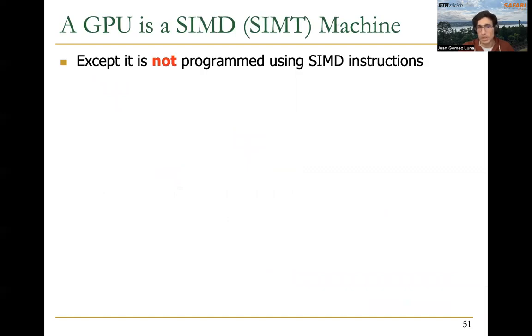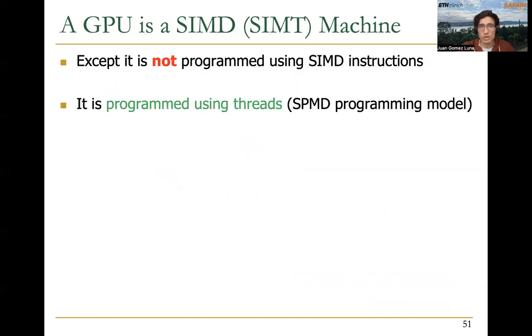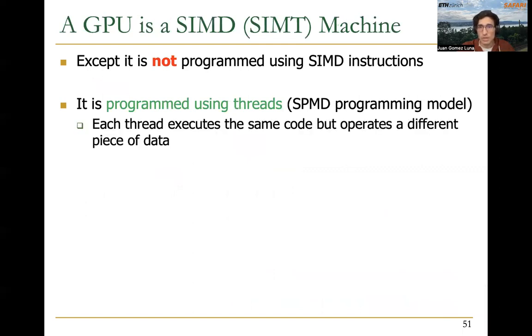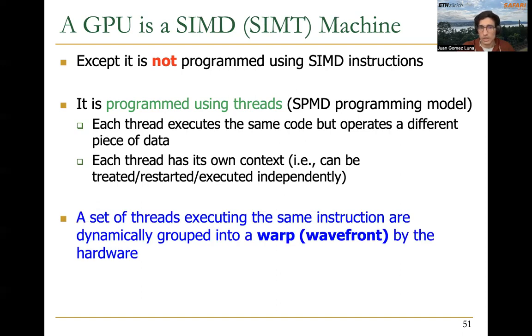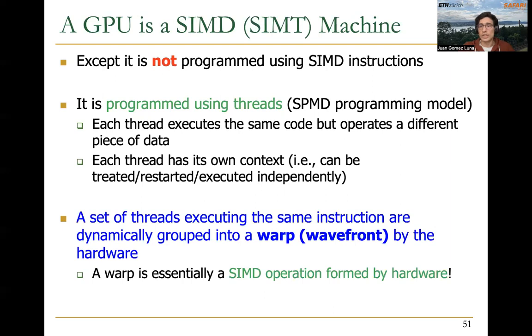The only exception is that it's not programmed using SIMD instructions, but using threads, with an SPMD programming model, where each thread executes the same code but operates on different pieces of data. Each thread has its own context, it has its own PC, and can be treated, restarted, and executed independently. But then the hardware is going to put many of these threads together, forming what is called a warp or a wavefront.